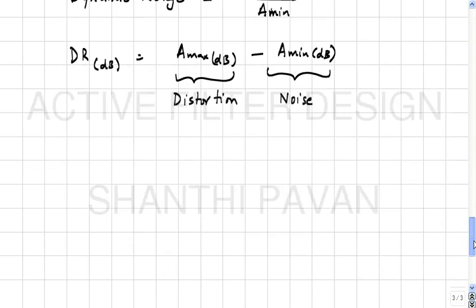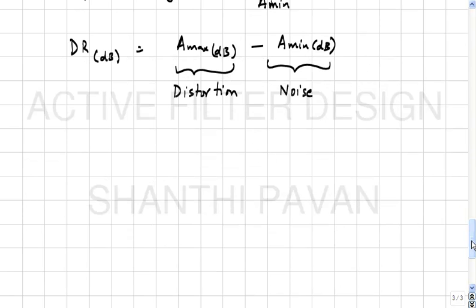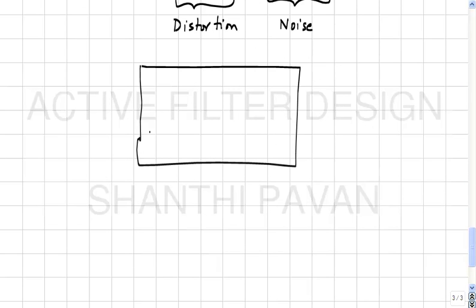Now, the question is, I have this filter. So, some Vi, it's got transconductors and capacitors. Okay. I have not put in resistors simply because I know that any resistor can be realized by taking a transconductor and connecting its output to the input in the proper sign.